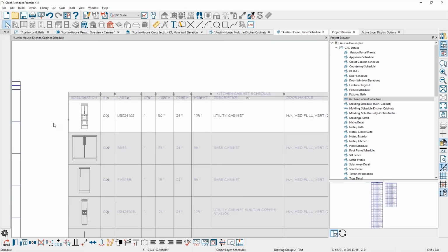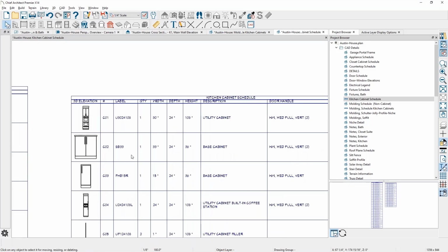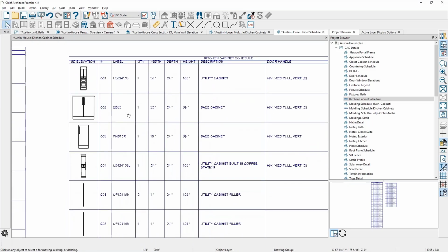So when I move that one to the top, it becomes C1. Got it. So depending on how you want those organized, you have to manually drag those up. It's difficult for us to automatically do that, because if you end up resizing one, deleting one, inserting one into the middle, oftentimes we don't know exactly what you're after. So that's how you control the label number. Okay, perfect. Thank you. And then just one last question.